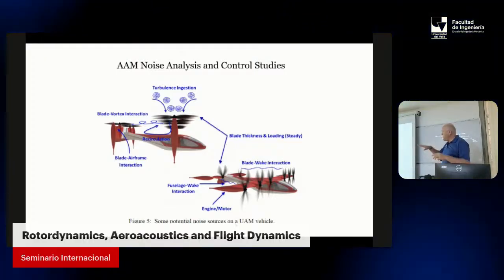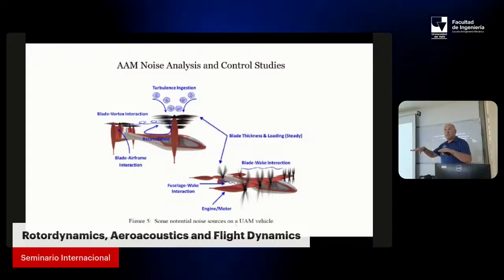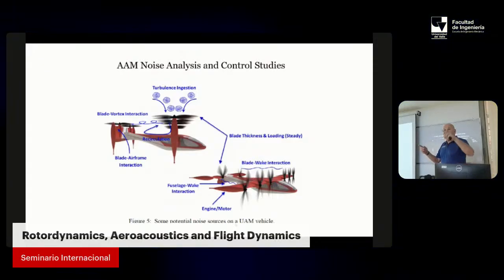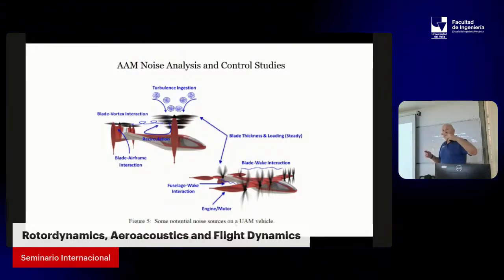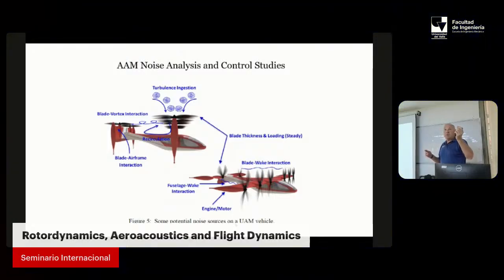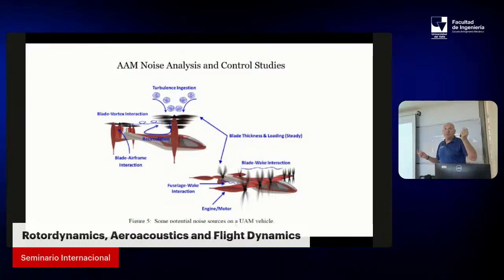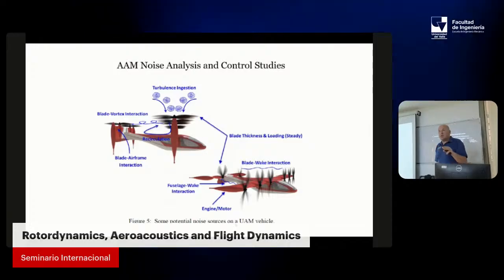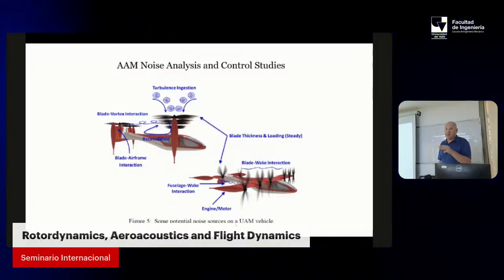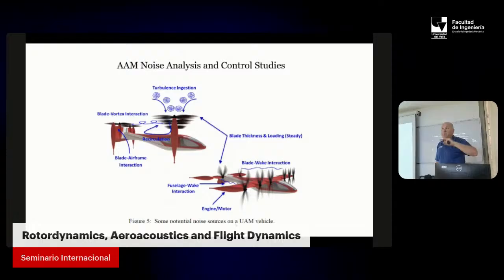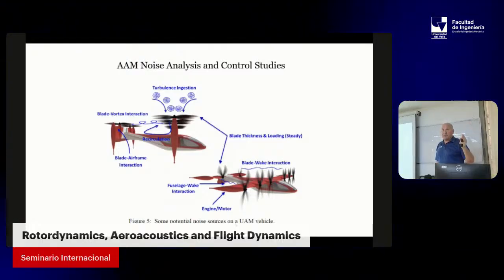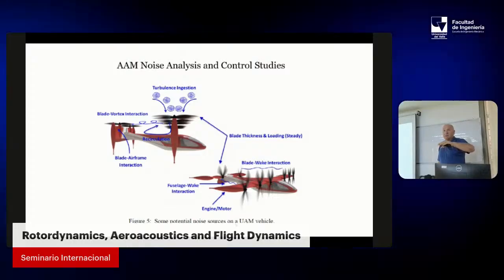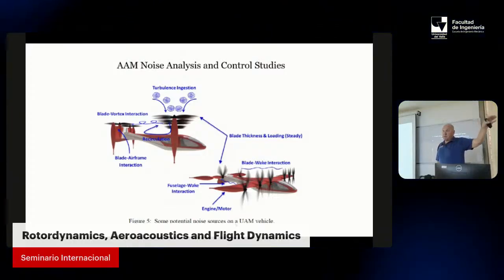So these rotors in this case will have reduced loading on each one because of the distributed framework. And it will be a low Mach number because you have low rotational RPMs. So you have not so much Mach number, maybe 0.3. So much reduced. So the acoustic signature is completely different. I'll show you that. The spectrum for the noise will be very different from helicopters. The primary tonal noise will be much suppressed. But there will be other things which exist.